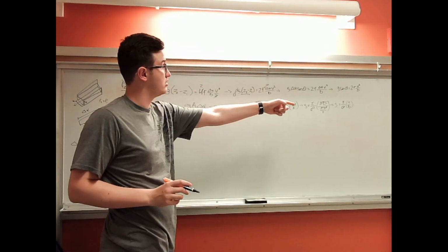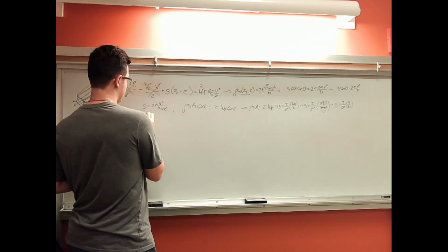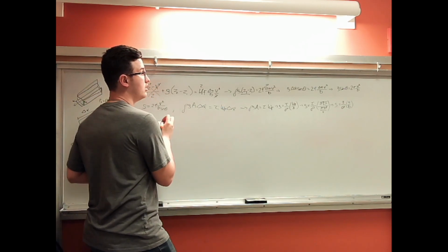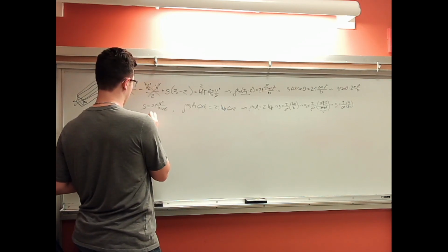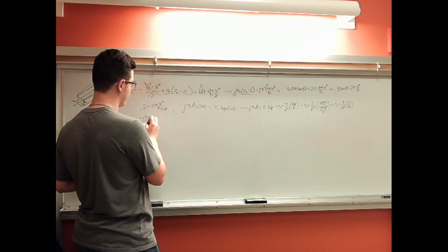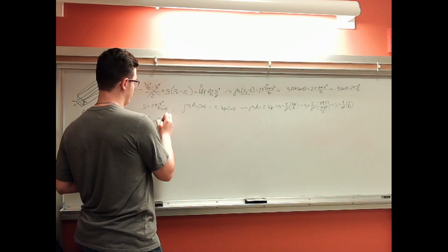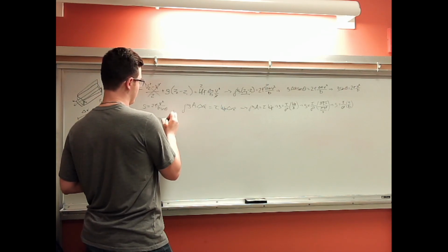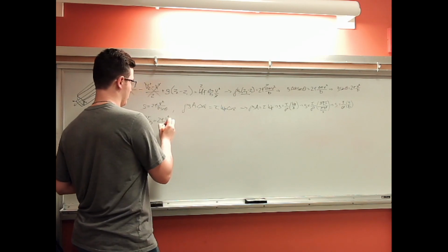We can now move along to tau, the shear stress. So that goes to tau, or 4 times the shear stress divided by density times diameter equals 2 times the Fanning friction factor times velocity squared over diameter sine theta.